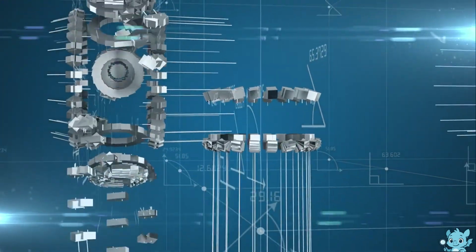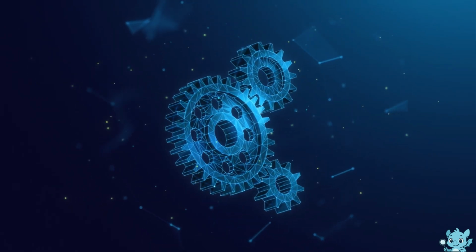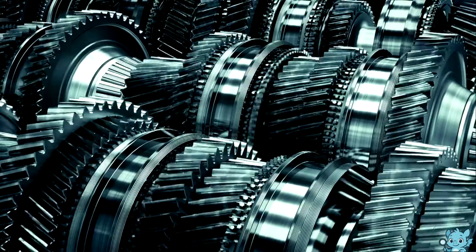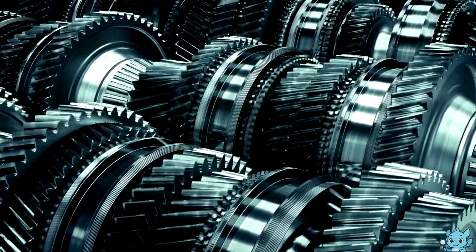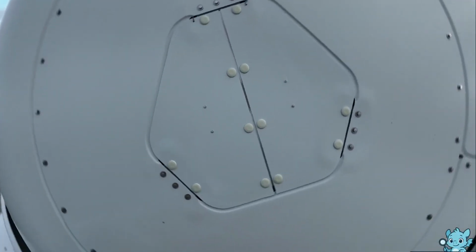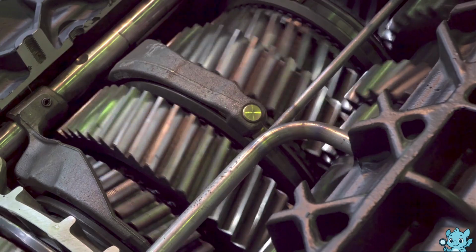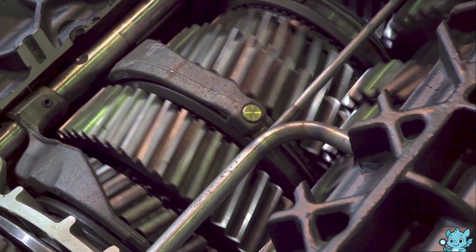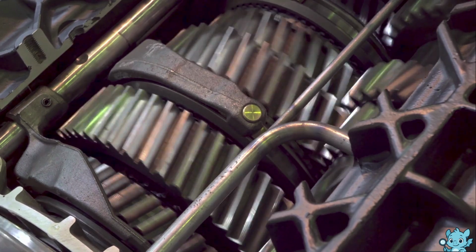The rotor turns a low-speed shaft that runs into the gearbox located inside the nacelle. The gearbox is essential because the rotational speed of the rotor is too slow to generate electricity efficiently. Gearbox function. The gearbox uses a series of gears to increase the speed of rotation from the low-speed shaft to a high-speed shaft. It typically multiplies the rotor speed by 40 to 100 times, depending on the turbine design. For example, if the rotor is spinning at 15 RPM, the gearbox might increase the output shaft speed to 1,500 RPM, which is ideal for the generator.